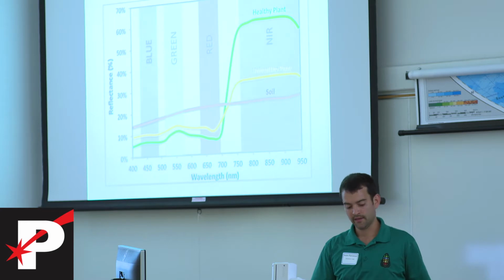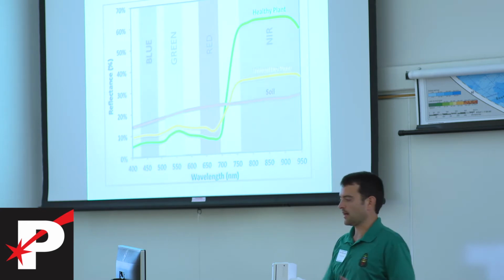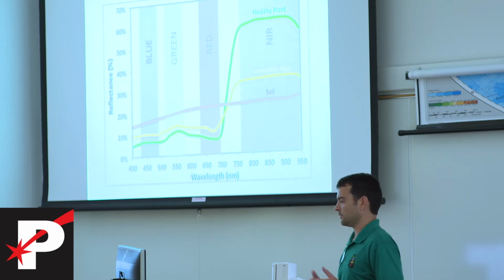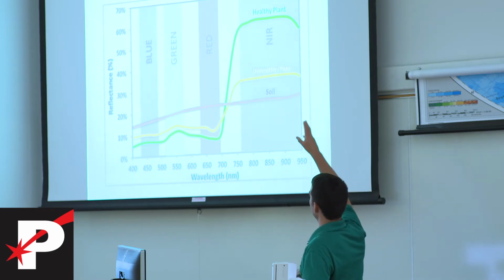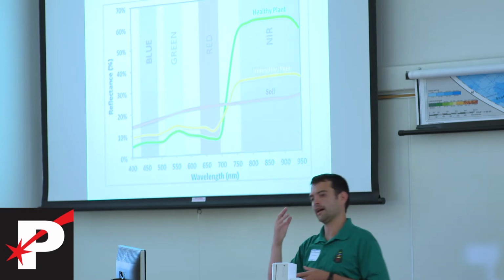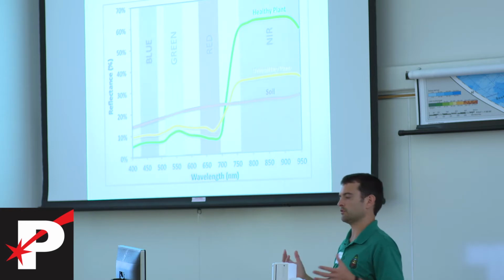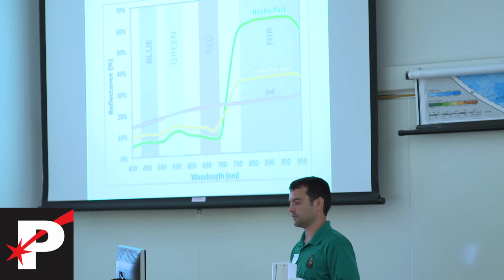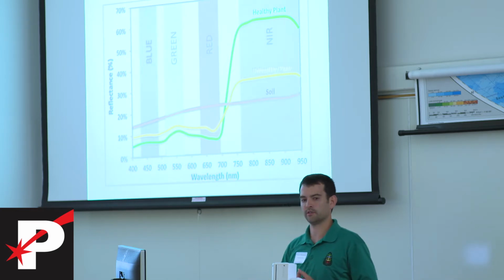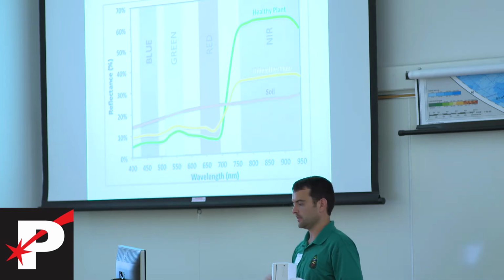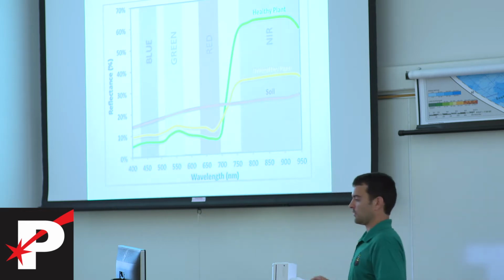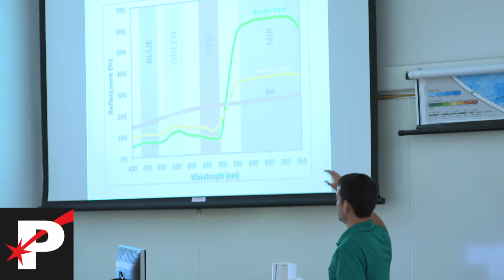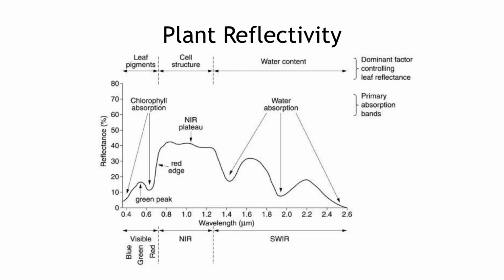So when we see a dead plant, when it's brown, it's obviously dead. But we can look at green plants and actually see a difference in health before our eyes can detect it. And that's what multispectral imagery and seeing that near-infrared spectrum and beyond is really important for: capturing information from vegetation. And of course, soil or any surface, asphalt, water, they all have different spectral signatures. Soil is, as you can see, very flat, and so even less reflective in the infrared than the unhealthy plants.